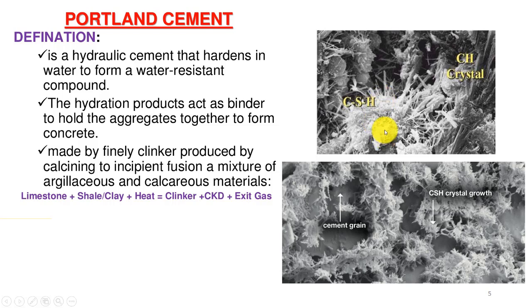Basically, SEM analysis is not photographic. You don't have a camera lens to take these SEM images. You just utilize high energy electron beams bombarded on your specimen, so that you can get the morphology of the specimen by imaging without camera-based imaging.